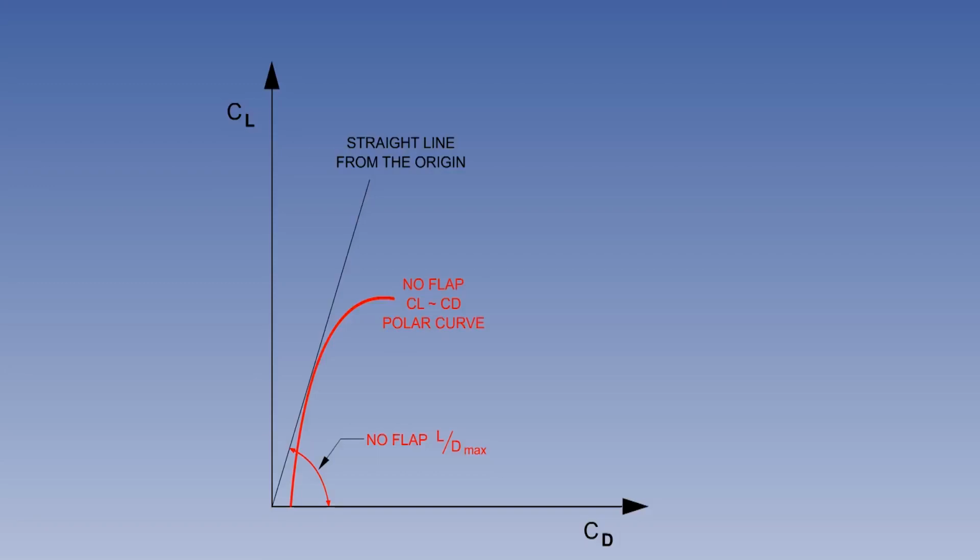We have already seen that CL max increases as the flaps are lowered, but unfortunately drag will also increase, so we need to consider LD max. We must generate enough lift to balance the weight, but at the same time drag must be a minimum. Therefore, drag will divide into lift the maximum number of times. We call that LD max.